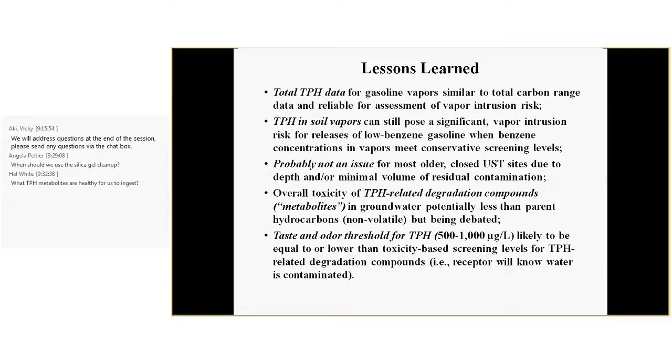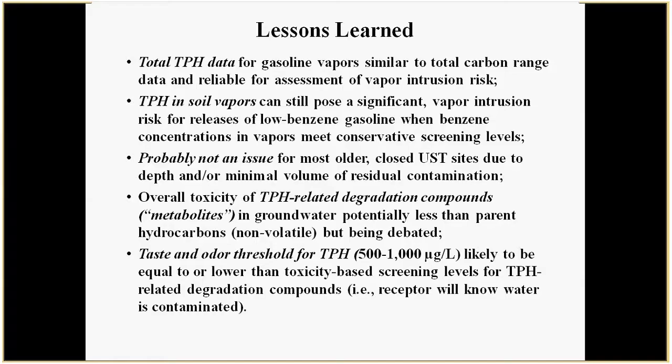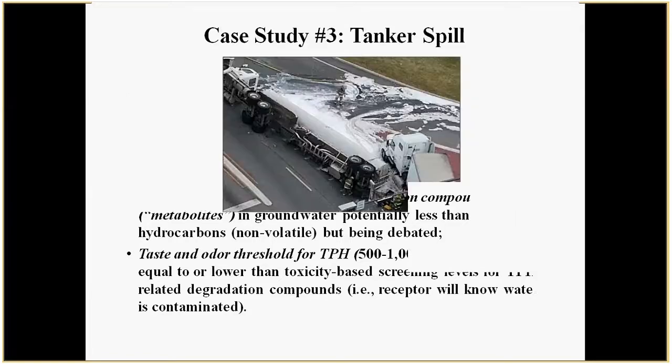The overall toxicity of TPH-related degradation compounds is probably similar to the parent hydrocarbons when you're close to the source. They could be less toxic as you move away from the source. That's still being debated and discussed. And in the end, the water is probably going to taste bad and smell bad by the time you get to 500 or 1,000 micrograms per liter anyway. So that was the gas station site.